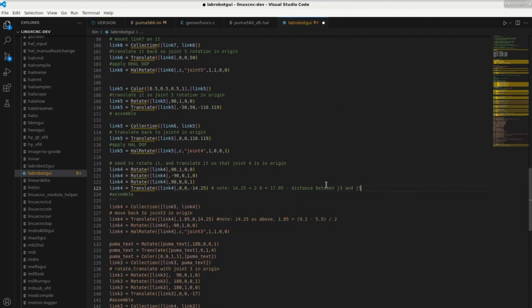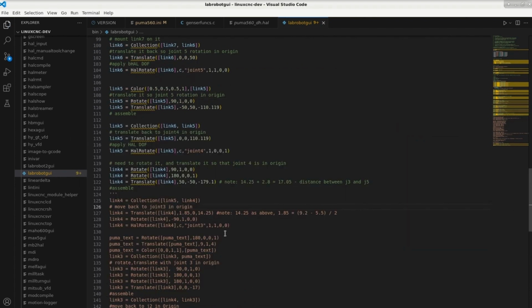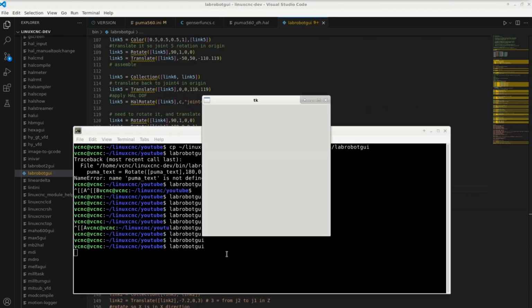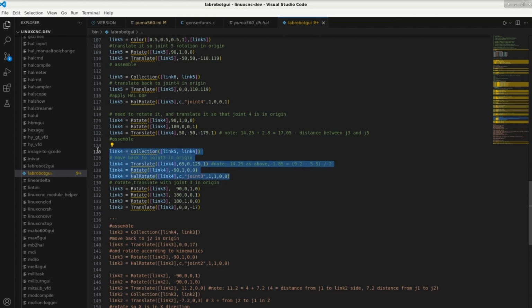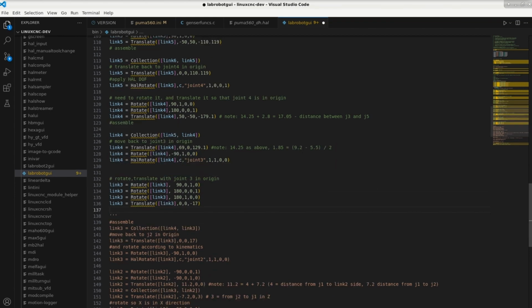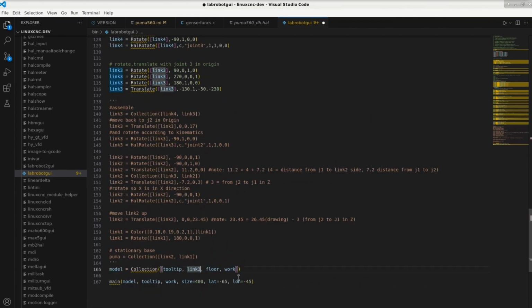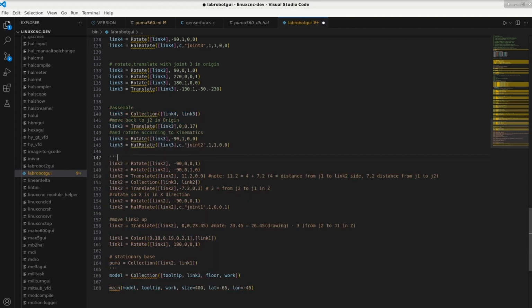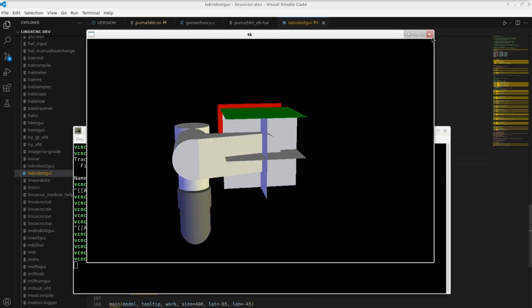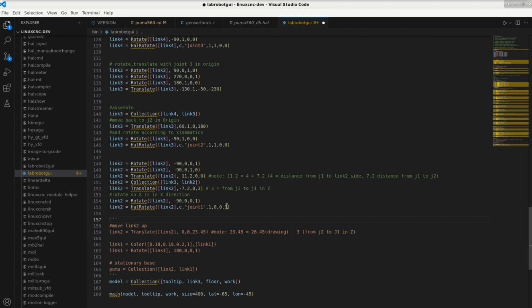The Puma simulation is in inches, so it makes sense to adjust the graphic resolution. It is also helpful if you insert some reference surfaces to be able to position the axis better. Step by step, we can put all the joints together until the complete model is assembled.